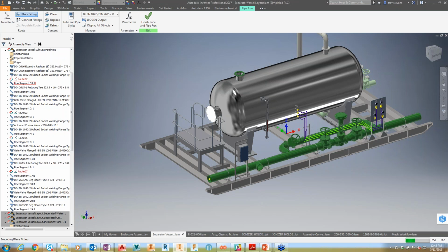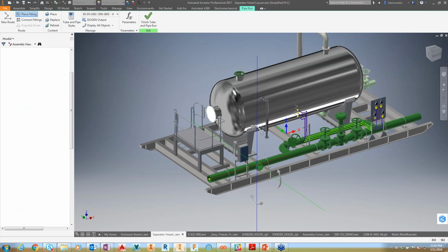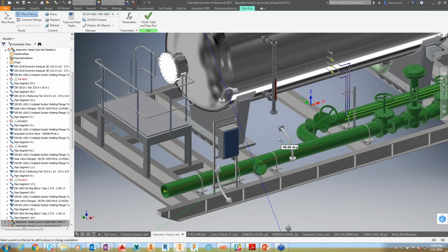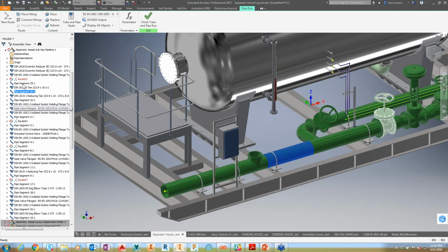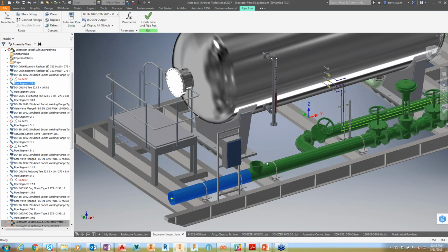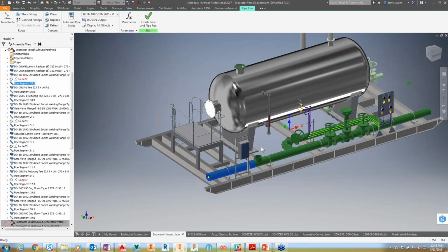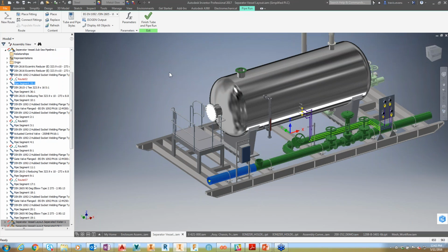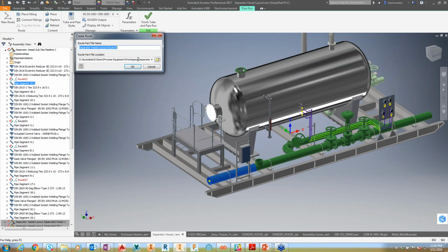So the other thing you'll notice is once I finish this design, and we rotate this to the 90 degrees that we want, so it's upright to go to that next series, the other thing that it does for us is it'll break up that pipe into two separate segments, right? So here's the pipe. We've got pipe 35 and 36 in two separate segments. So it's intelligent enough to know how that was joined. And then because I chose to weld these two joints together, it's going to weld that information in, as I'll show you some of the different styles you can do as well. So now I want to create a new route.